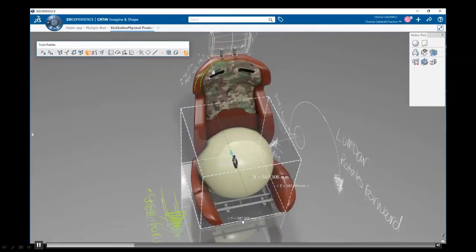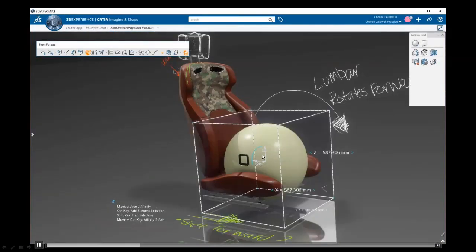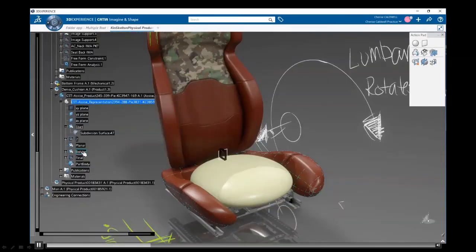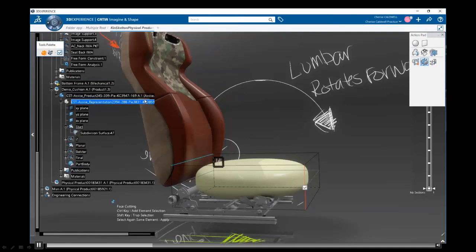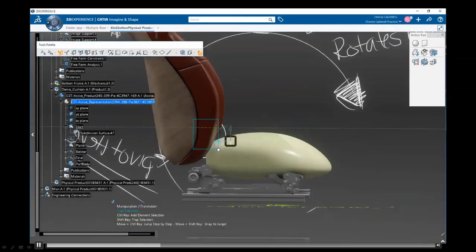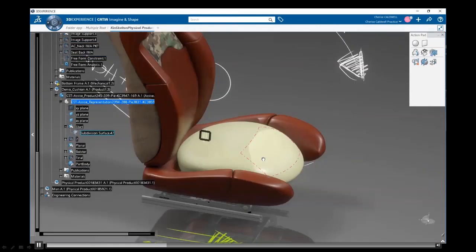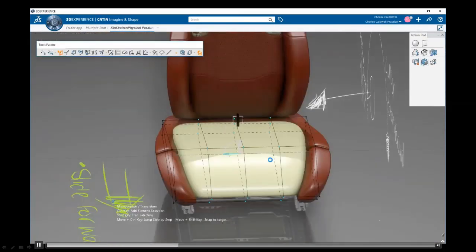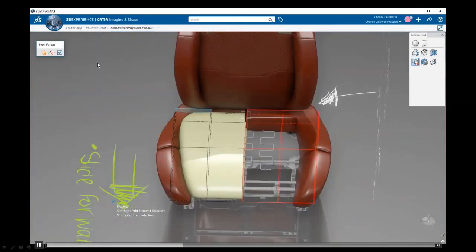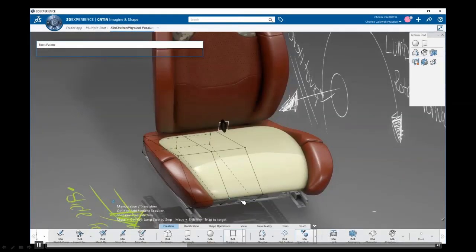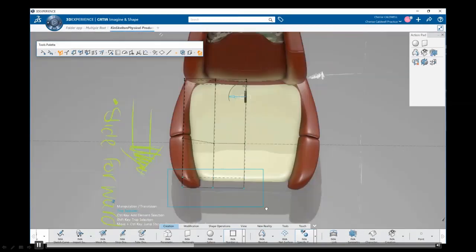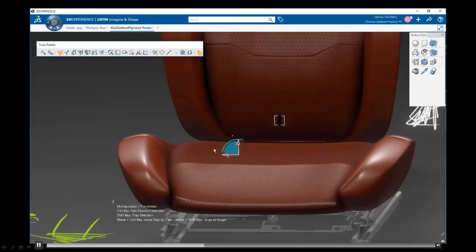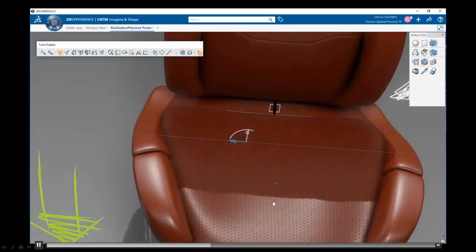Now we're going to go ahead and model the seat cushion. This time we're starting with the closed volume. It's up to you. You can have an open skin or closed volume. It starts out very simple, but we can change our perspective of our view. We can add what some might refer to as edge loops. In CATIA, we call them section cuts. And so we can increase the resolution of that surface. Now we're just manipulating this cushion. With or without materials applied, you can see the perforated material on this seat cushion.